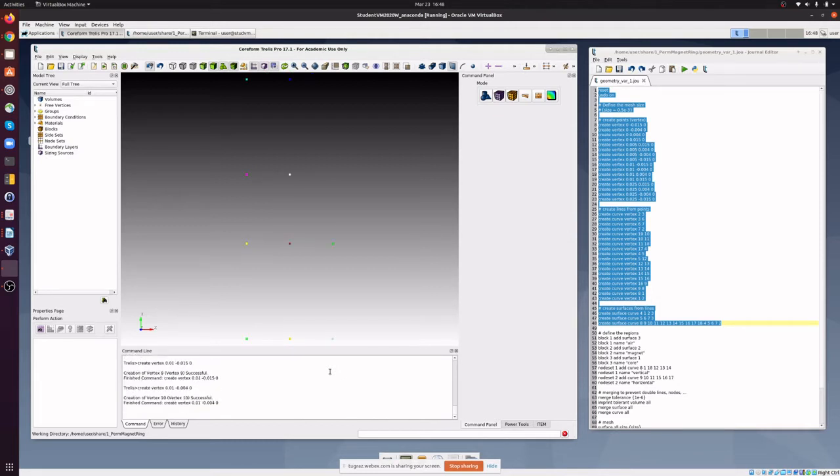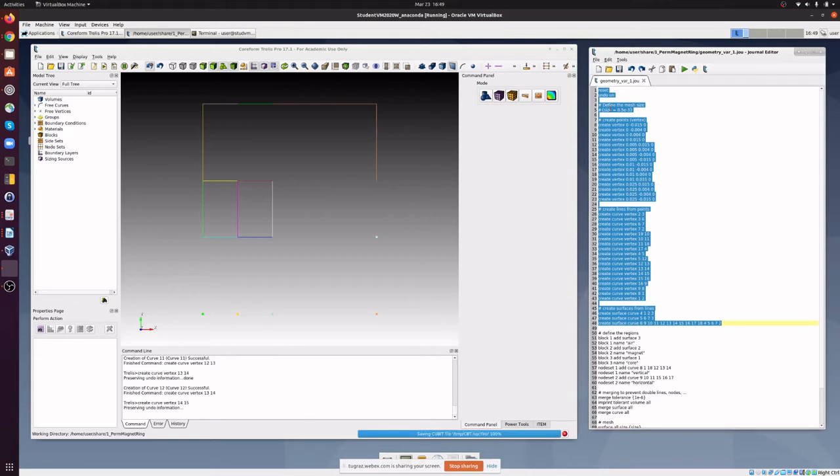So you can define variables in such a way: you write this hashtag and the curly bracket defines the variable name. In this case, the only variable we are using is the variable called size, which is used later on here in line 69, where we define the mesh size.